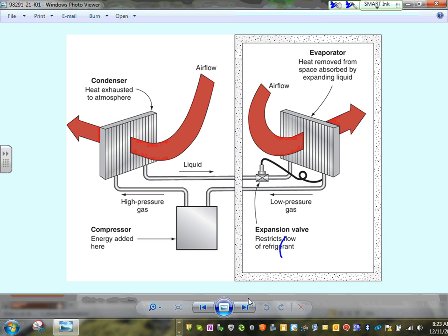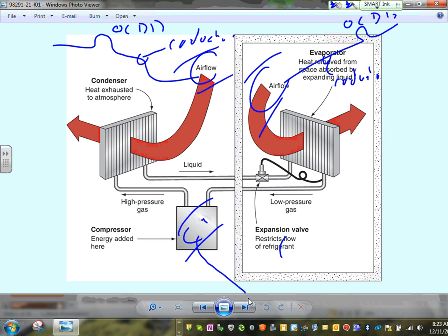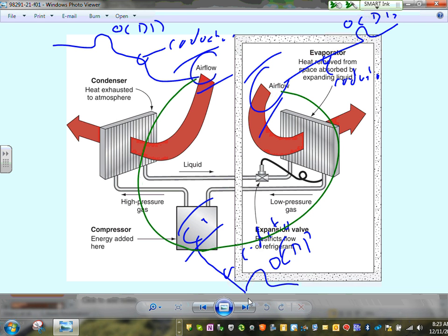Take this. We have a fan here that you, my friend, have to put an overcurrent protection device and a conductor on. That's number one. You have a compressor here that you have to give an overcurrent protection device and a conductor. And you see what I mean? And all the wiring in between, and all of it will be wired control, all the controlling system in between.